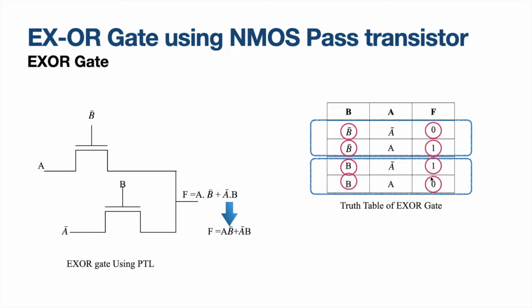This output remains the same as the output of a normal XOR gate. When we have two inputs and both are different, that is 0, 1 and 1, 0, for these two combinations alone, the output will be 1. That is why we call XOR gate an inequality detector. For the other two combinations of 0, 0 and 1, 1, we should have the output 0 and 0. So, right now we have converted all zeros and ones to B bar, A and so on.